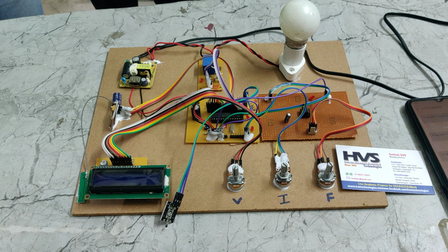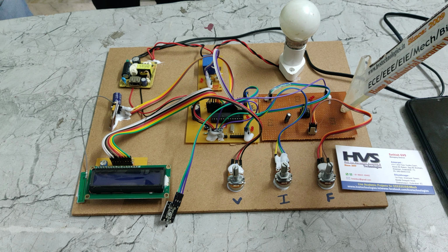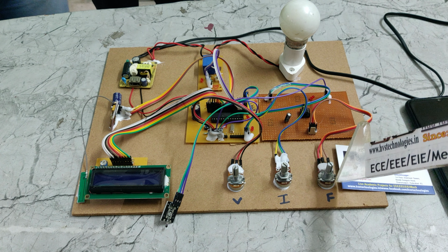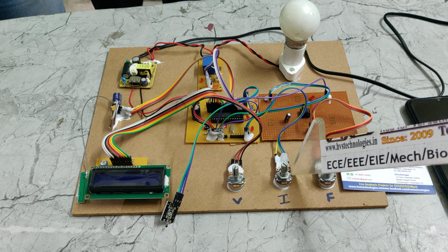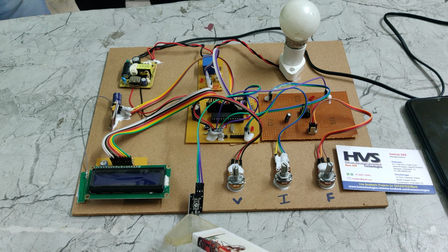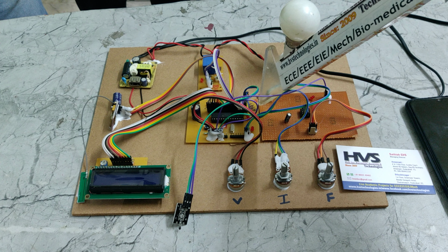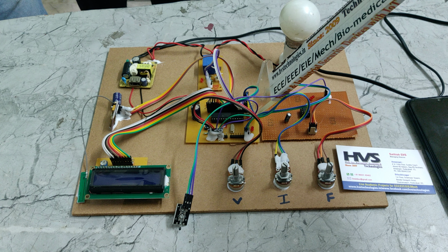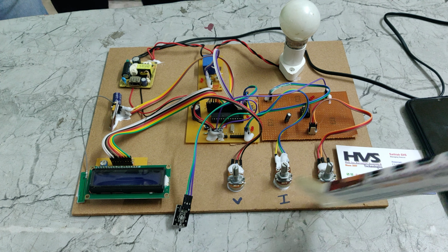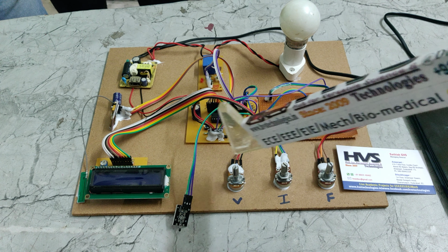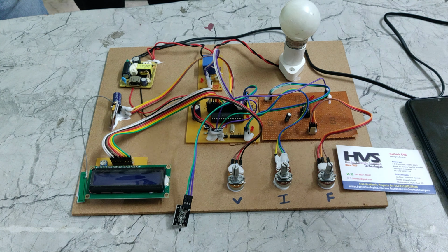Here are the main components. For frequency measuring and varying purposes, we are making use of this 555 timer, which gets input from this potentiometer. The voltage and current are varied directly using potentiometers, and temperature comes from this temperature sensor. This is the LCD display along with the driver, interfaced to the PIC microcontroller. We are using the PIC 16F73, and we have interfaced the four sensors to pins A0, A1, A2, A3, and B2 to B7 for the LCD and sending SMS alerts.